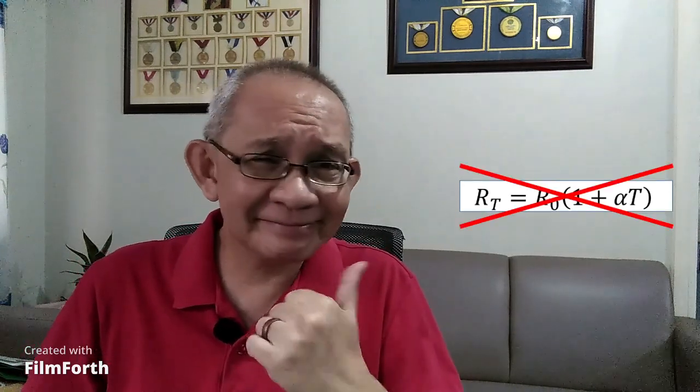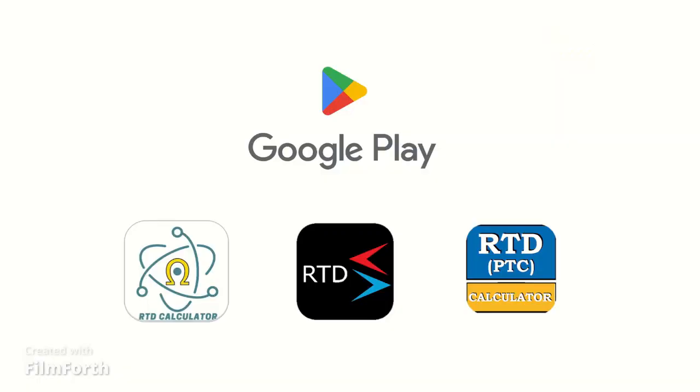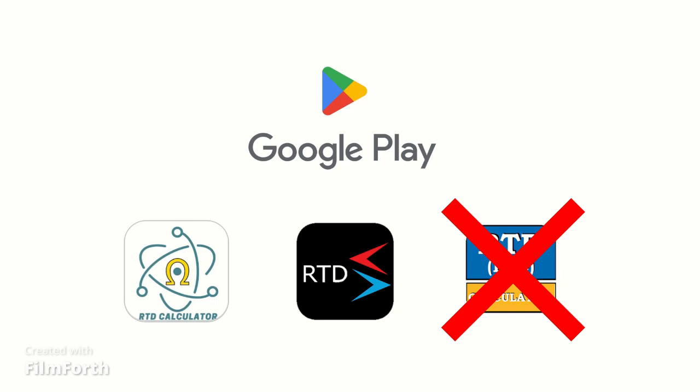Okay. So we've proven that this equation is no good. What methods can we use to determine the resistance of an RTD at any temperature? The first method is to use an RTD converter app from the Google Play Store. But you have to be careful because some of those apps use this same equation to calculate the resistance, and that means it will give you the wrong results.